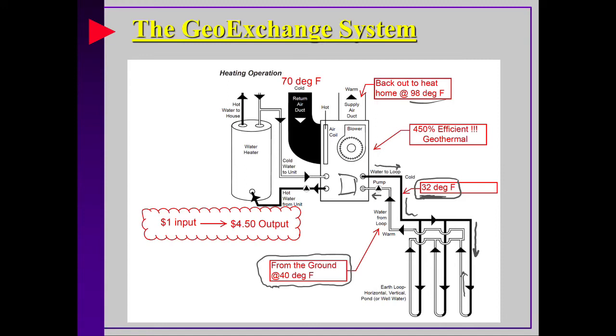Now, the heat pumps also have the ability to take water using that de-superheater loop. They can take some of that, anywhere from 55 to 110 degree water, and bring it into a de-superheater coaxial coil, and then pump that right back into the unit. So it might come out of the unit and feed the unit at 110, 120 degrees, and it'll extract those BTUs, so it works pretty good.